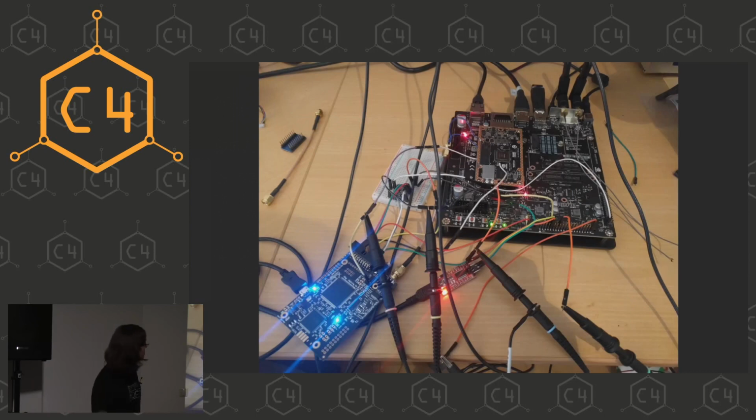This was my setup, a bit messier, but also a lot simpler. This is the board again, a bunch of oscilloscope probes to look at stuff. Serial port adapter, some voltage level shifting, just because everything here runs on 1.8 volts that I cared about. And this ChipWhisperer here, which does the glitching. This basically does the reset, glitch, adjust timing loop over and over again, controlled by some Python software.